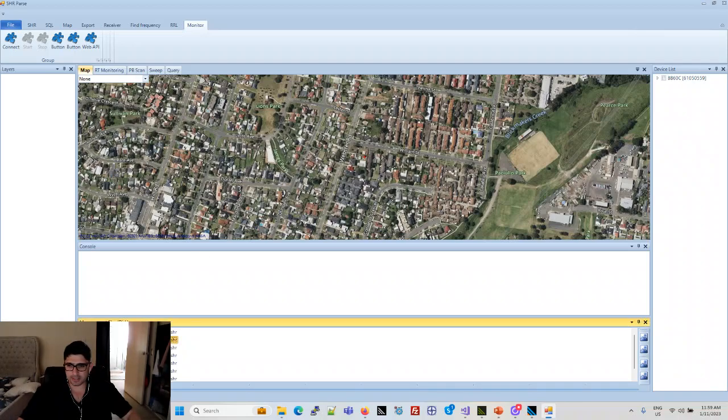This measurement here, for example, was done. You can see where the file is. You can see the number of sweeps. You can see the frequency range. You can see the header here. You can extend the header. So in the header, I can see the first bin, center frequency, and the center frequency of the sweeping, the RBW, reference level, and so on.